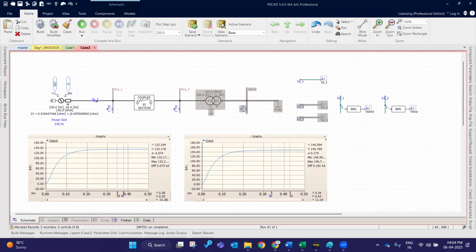Power factor correction capacitor banks are available in the master list. So in PSCAD, modeling the basic capacitance is enough to model it as a power factor correction capacitor, right? There is no specialized tool for power factor correction capacitor at all. Directly, we will be modeling the capacitor. Before that, we will be validating that capacitor. That entire network we will be validating, and then proceeding with our network.